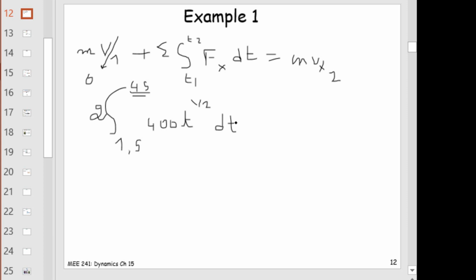What are the remaining forces in the x direction? Don't forget that I have the frictional force, and now the frictional force is equal to mu k times N, and mu k is equal here to 0.4. So minus 0.4. Why is it minus? Because in fact it's in the negative direction of x. And don't forget that N will always be the same, even in the dynamic case, because there is no acceleration in the y direction. So this crate is not moving in the y direction, which means it's always in static in the y direction.